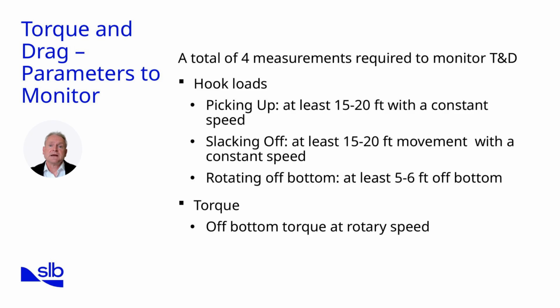By comparing them against modelled predictions, we can identify deviations that may indicate poor hole cleaning, cuttings accumulation, or tight spots. Accurate monitoring ensures that engineers can respond proactively, adjusting drilling practices, fluid properties, or string design before problems escalate into stuck pipe or lost time.